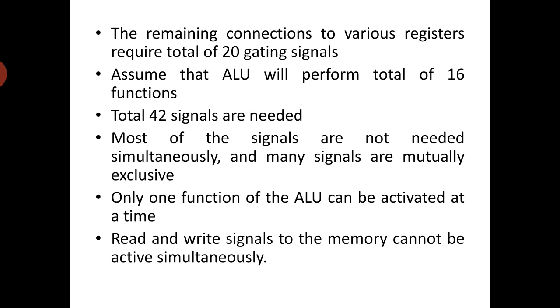So this discussion suggests that signals can be grouped. We can group the signals so that all mutually exclusive signals are placed in the same group. Thus, at most one microoperation per group is specified in any microinstruction.